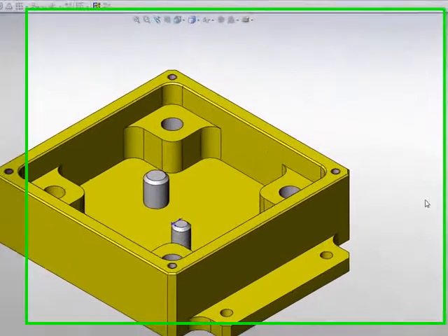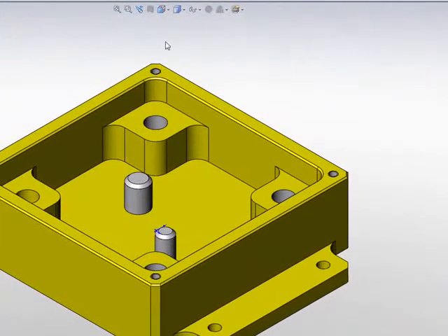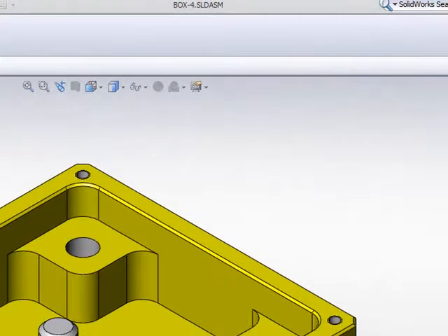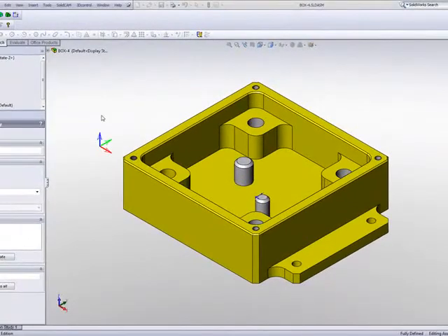Now, the geometry in itself has to be a boundary around the area that has to be face milled. So if I want to take the entire part, say the entire model, since I've created a target in the very beginning, I can simply go and have the model checked off as shown here and choose target.